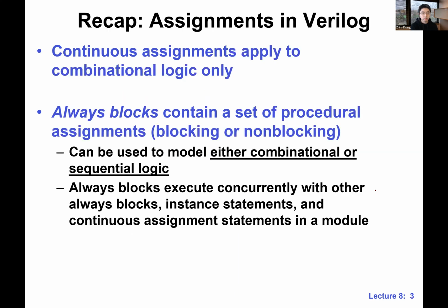Okay. So let's talk a little bit more about Verilog. Last time I gave you a very quick intro. We just quickly went over some of the concepts. Then we focused most of our time on the so-called procedural assignments in Verilog. We actually talked about both kinds of assignments. So one more for the computational logic, that's called continuous assignment, where we basically have something called assign. So this is a keyword, and we also introduced another important keyword called always. This always block is very important for us to create meaningful designs, including both computational and sequential design in Verilog.